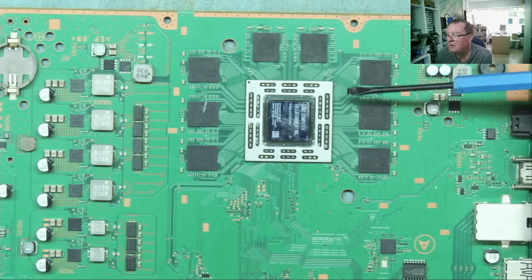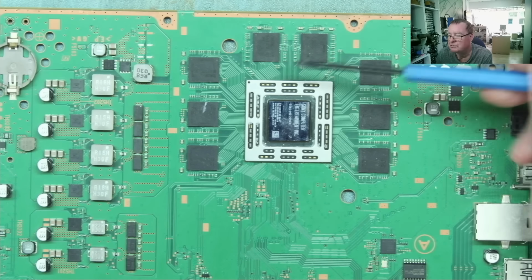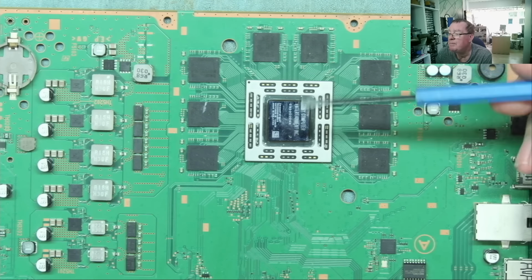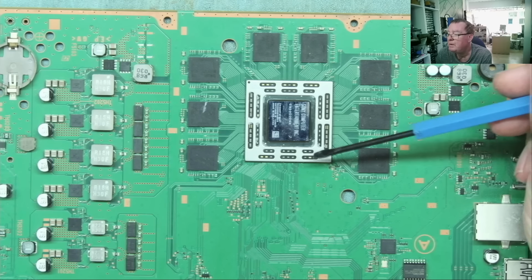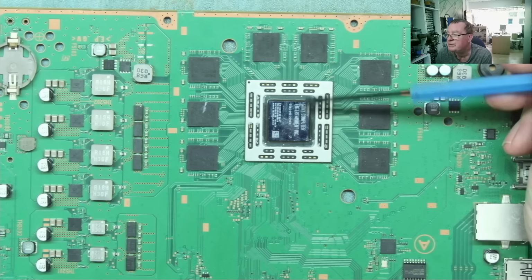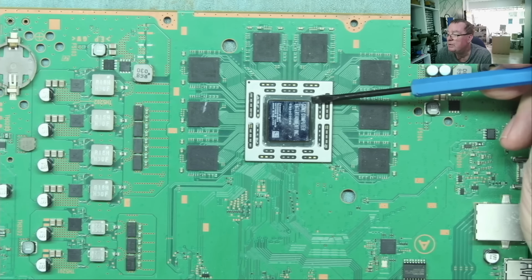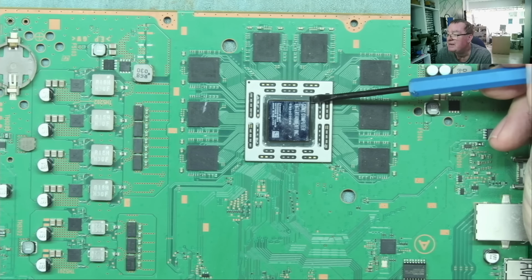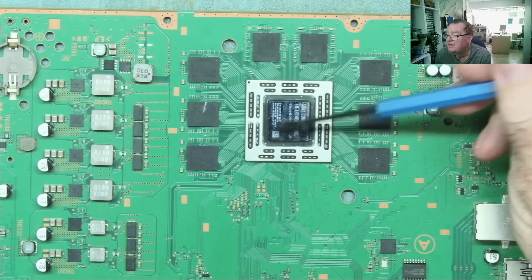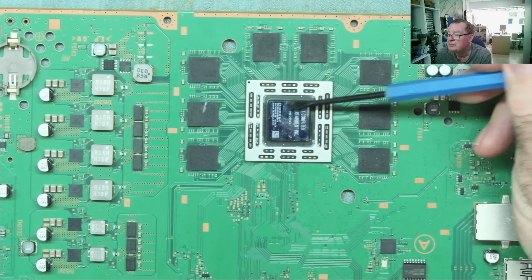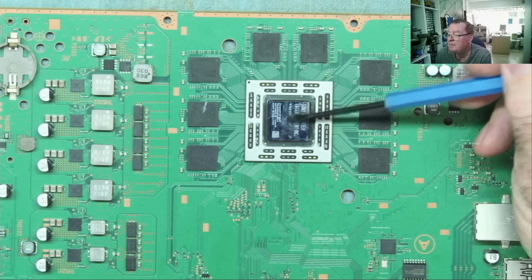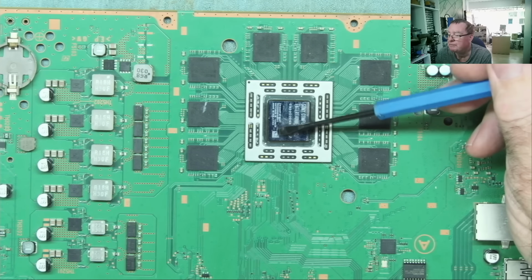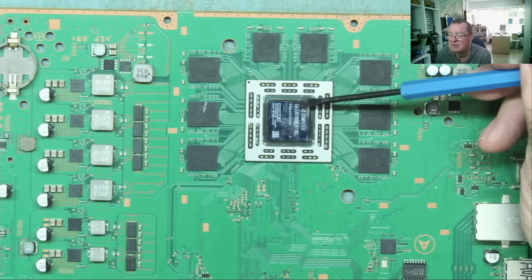So in the early 2000s, NVIDIA in particular had a problem with the design of their BGA chips, and the problem was to do with the substrate. That's this green stuff you can see here, and the die, that's the thing which actually contains the millions or billions of semiconductors, transistors, or the MOSFETs is there.